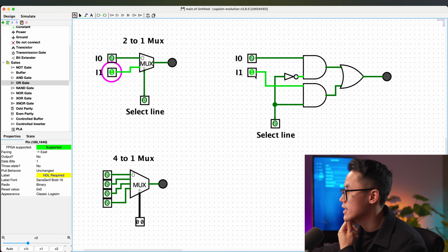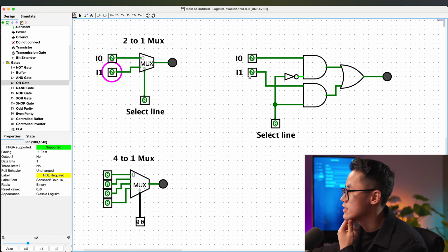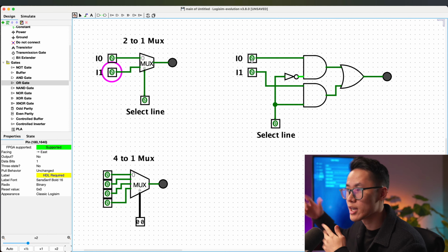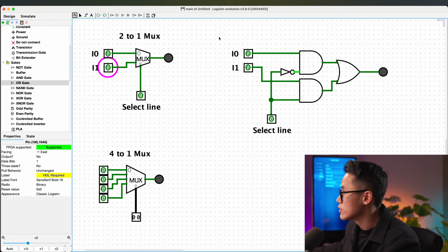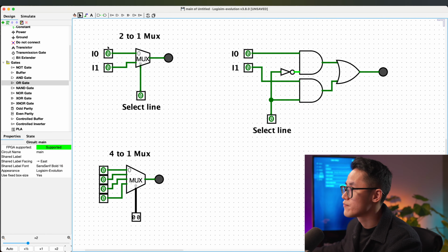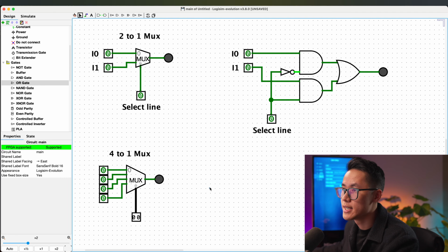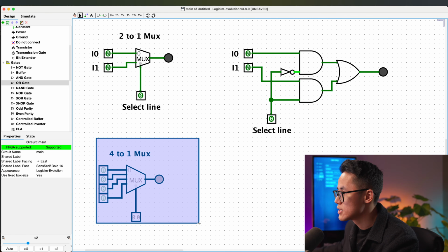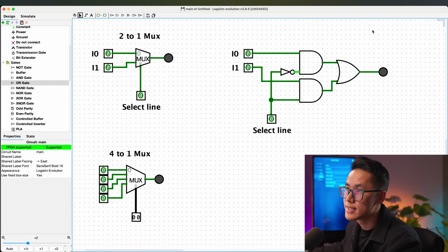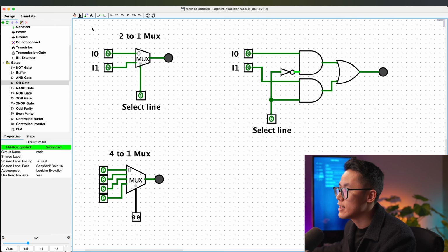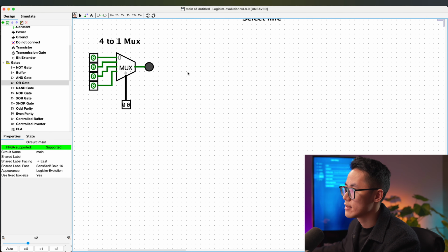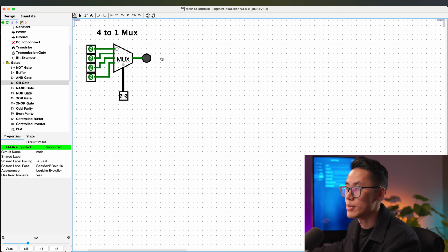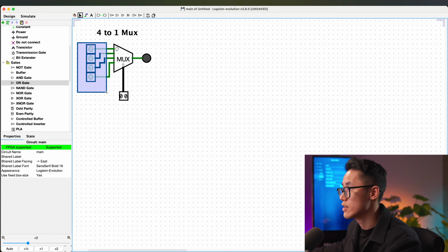If I turn the second one, it doesn't change, so it's good. It's just forwarding the first one and it disregards all other input. Okay, so that is what you have to do for a 2-to-1. I will create a 4-to-1 mux just by using these gates. And in the lab exercise, you will create the 8-to-1 mux. But now I will do this one together with you.